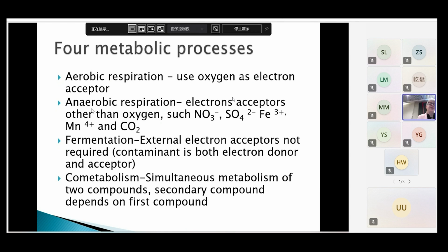So there are a whole set of mechanisms: fixation, solidification, stabilization, and so on, which you're doing by adding these agents to your soil for stabilization purposes. So you're doing a physical entrapment and a chemical stabilization at the same time. You're adding all sorts of things like fly ashes, and so you have absorption, you have precipitation, you have detoxification, and you have all sorts of binders and sorbents that you're adding. So the most popular solidification method is to add Portland cement.